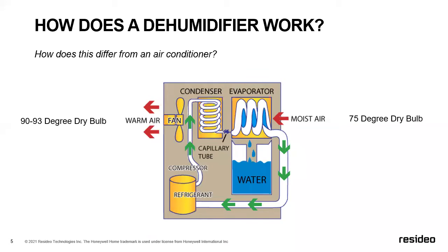So that air, one of the questions I get is what should the air temperature be on the outlet of a dehumidifier from the inlet? And typically what we see here is a 15 to 20 degree rise, which is kind of the delta. When we talk about delta, it's air in, air out. What's the difference in those two values? And so our dehumidifiers are really no different.